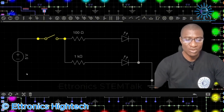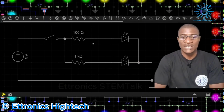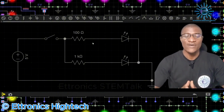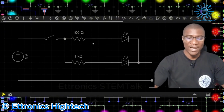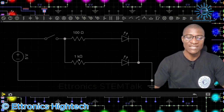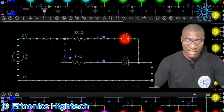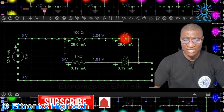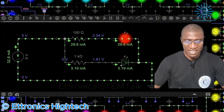So we will simulate the circuit and we will see how current flows in the circuit. Remember, we are trying to demonstrate that more current tends to flow through the path with the least resistance. So we have two paths here. We have the path that has 100 ohms resistance and we have the path that has 1000 ohms resistance. So I'll run the simulation and boom, you can see from the current flow indication that in this direction, we have more current flowing than the current flowing in this direction.